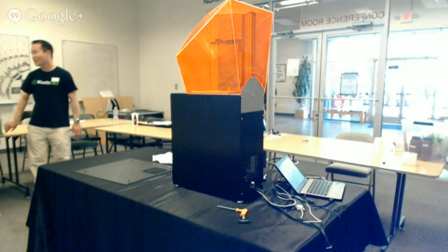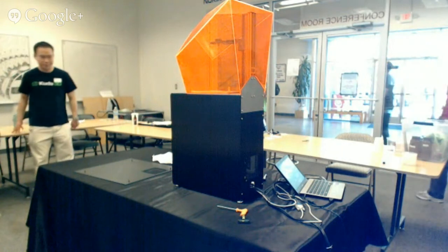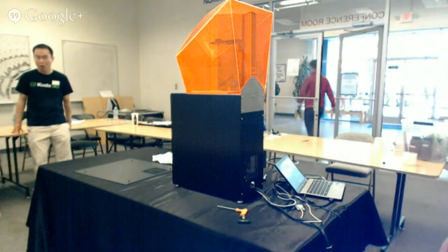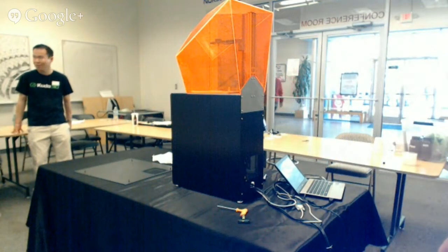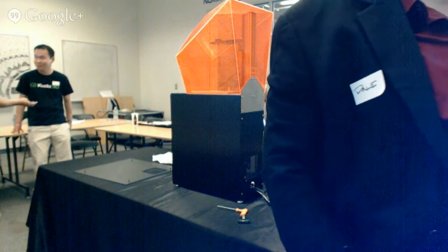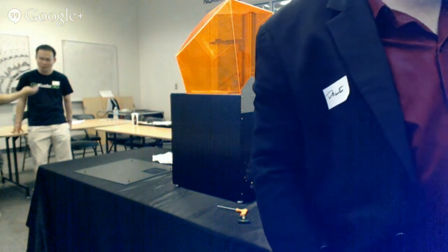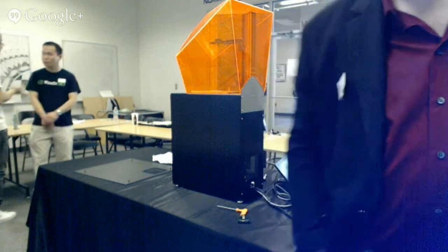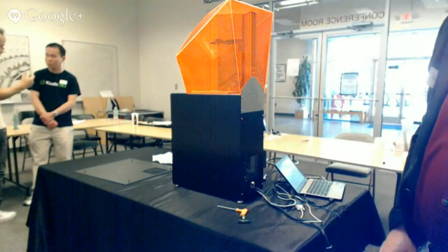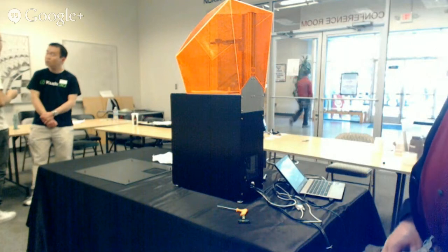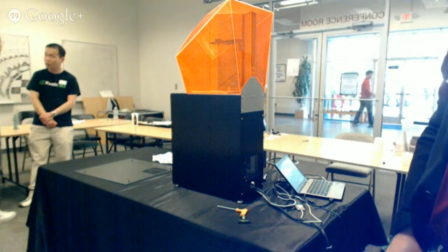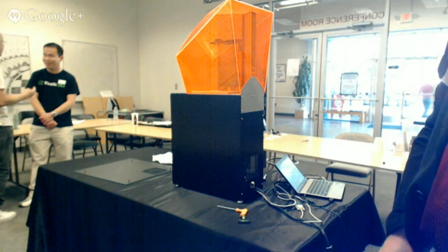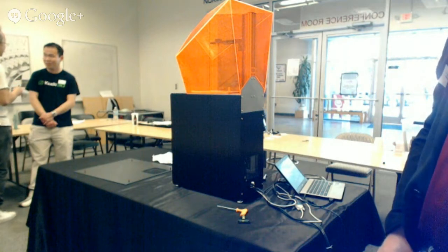One factor is that an image like this is not uniformly bright across the entire surface. This picture here varies probably by 20% between the brightest and the dimmest portion, right? We don't see it clearly looking at this, but resin knows. It makes a difference to the resin. And some projectors use dimming masks, putting a mask to dim down the brightest portions to make the image more uniformly bright.